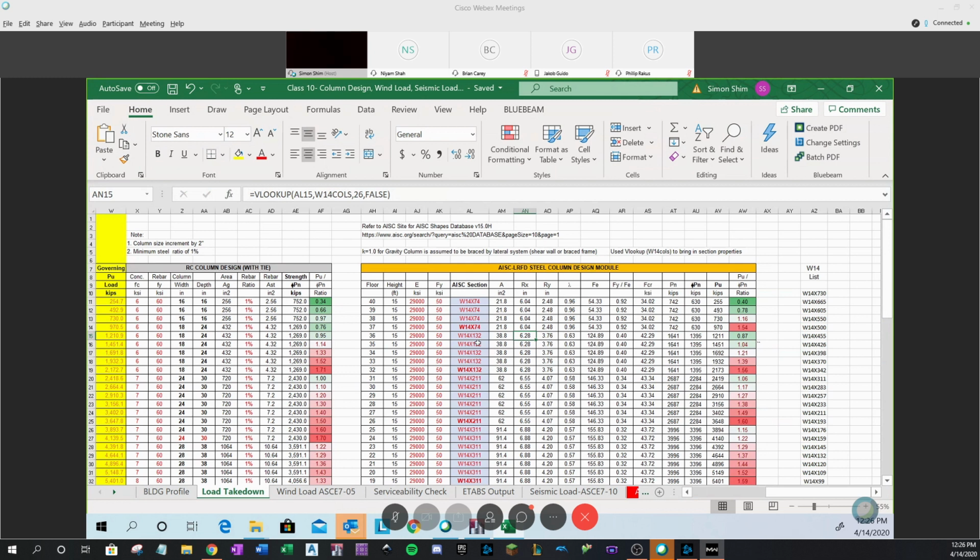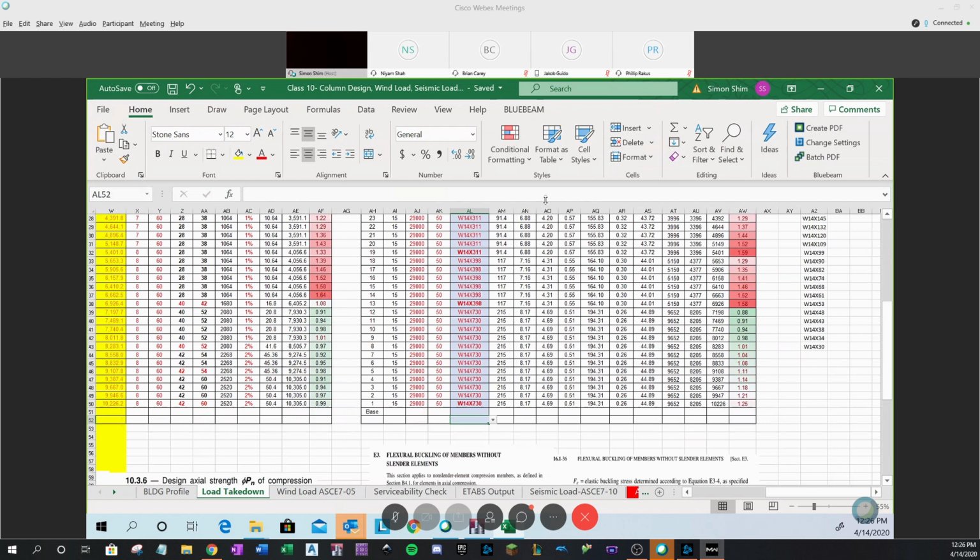Mm-hmm. So this case is something unique, because if this is obviously a small building, you could find a workable W14, right? Because now our force here is 10,000 kips. Okay, here are the column reactions, all the column forces. So even with our heavy section here, you see that it is 25% over-stressed, because this W14x740 is not enough for our force.